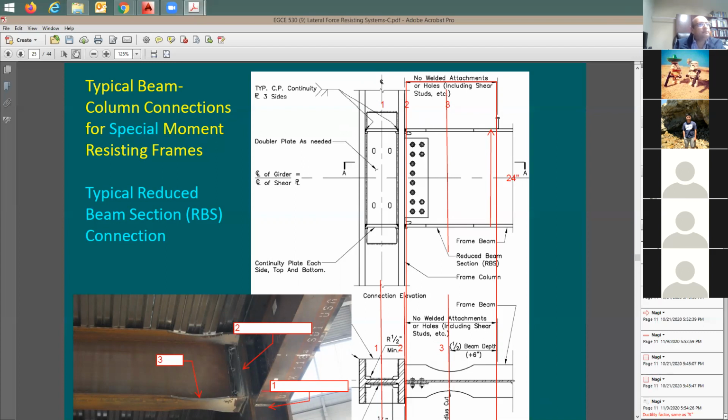Okay. But sir, we do have a cut on the flange of the beam in the protected zone. Actually, you know why we're doing this cut? Yes, sir. So it is protected, which means don't weld anything. It does not mean don't cut it this way. We really have to cut it this way. Otherwise, we don't have a place to dissipate the energy, and the dissipation of energy is going to happen right at the welded connection, which is not good.